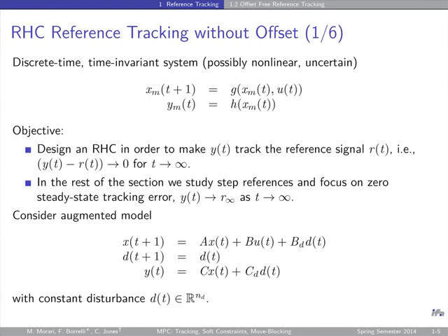I will use exactly this expression, which I know is the steady state condition satisfied by my observer. This is what this observer will converge to. I will use this to define my targets for my controller. And what else I changed, obviously, is that I changed the measured output to my desired reference. That gives me the target. I want eventually my measured output to be my desired reference. This is now the system of equations I will add to my MPC equations, just like before, to define my X target and U target, which will then appear in the objective.